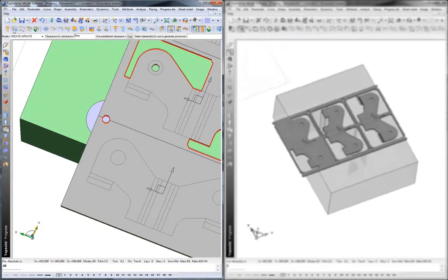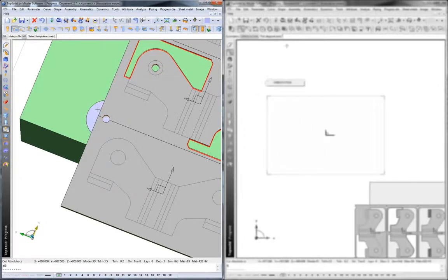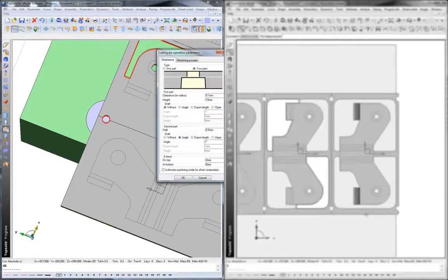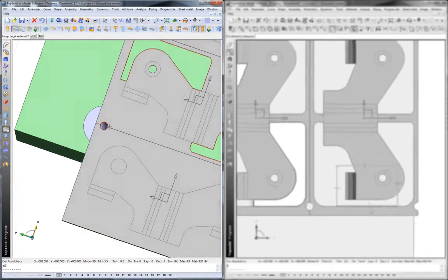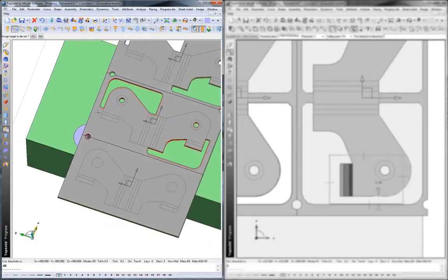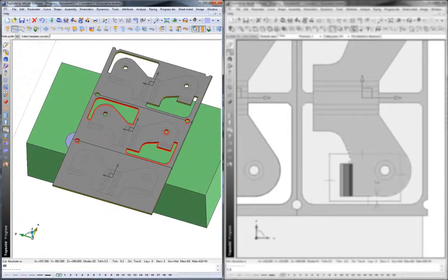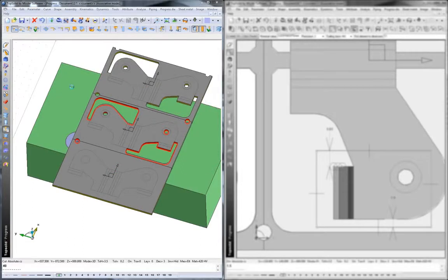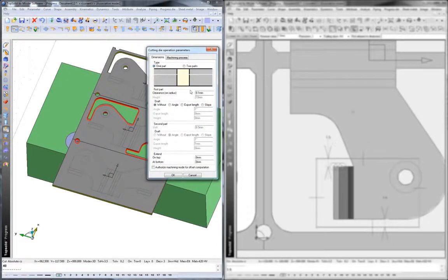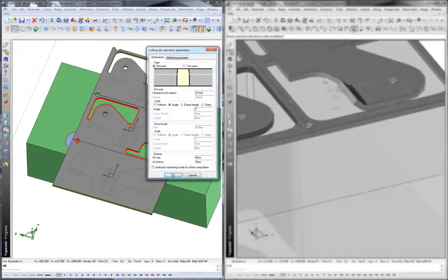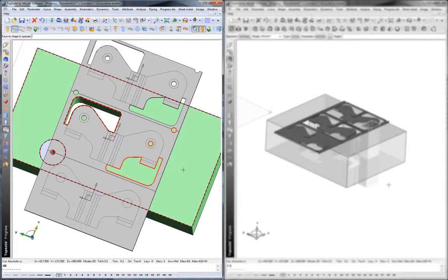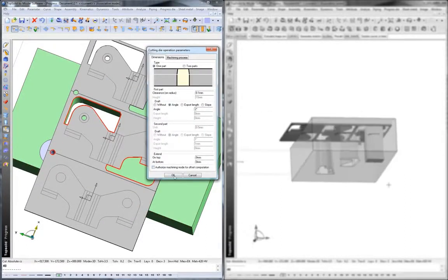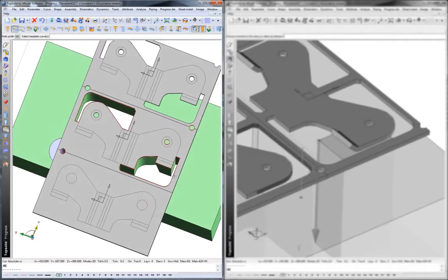Yes, let's make our actual relief through there. So we'll select that, we'll select the plate we want to modify, or this new insert that he made, and we'll choose how we want to relieve that. Like that, TopSolid Progress does the work for us. Let's keep going. Let's maybe make this cut out. In this case, maybe what we want to do is give it an angular relief. How about 2 degrees? Perfect. Let's do the same thing over here. That profile to that die block, same settings, and validate.